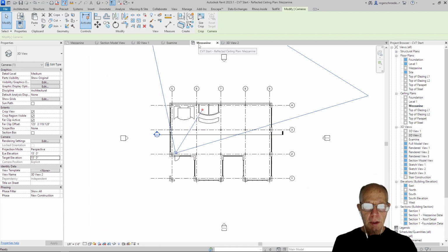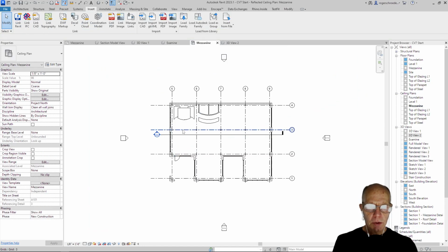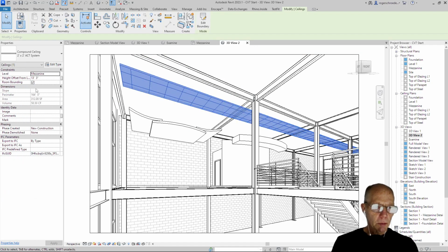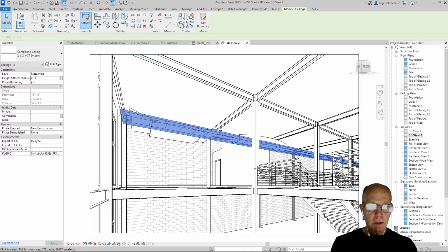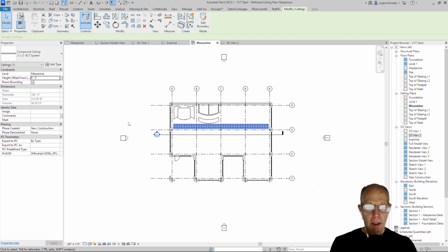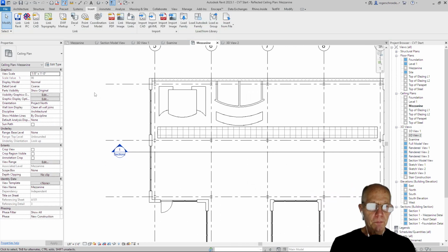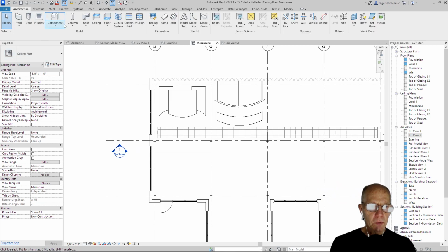And then we'll go to the mezzanine level, and we'll find out actually that our mezzanine or our aisle grid system isn't showing. And I believe that is because it's in a position that's just too high. So what I'm going to do is lower this down. It's 13 feet, so let's remember that. I'm going to move it down to 8 feet. And let's see if that shows up in the mezzanine level. And now we just need to move that back. I've just pulled it down low enough so that we have it in the view. And now we're ready to place our trofer lighting fixture.